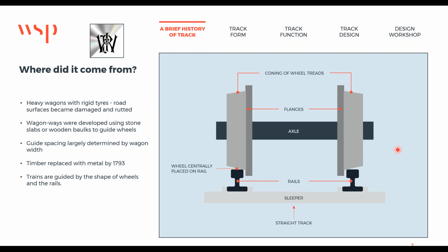But the wheel flanges aren't actually intended to come in contact with the rails and provide guidance. They do provide a bit, but they're a safety feature, something of last resort, which prevents the wheels becoming derailed. The vehicle guidance is provided by the shape of the track, obviously, and by the cone shape of the wheel tyre and the railhead being inclined towards the track centre. And I know it's not in that diagram, but I couldn't find one that was.